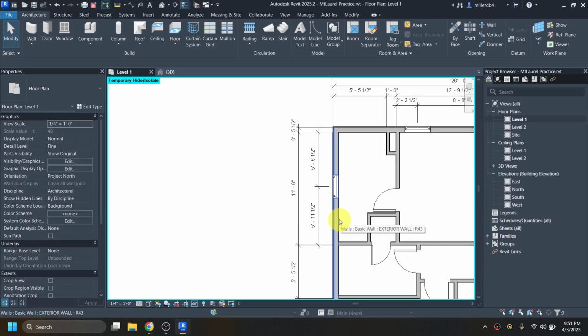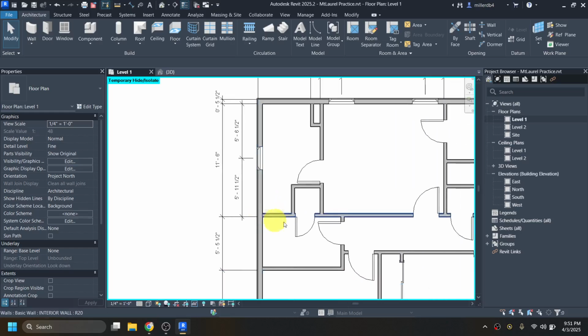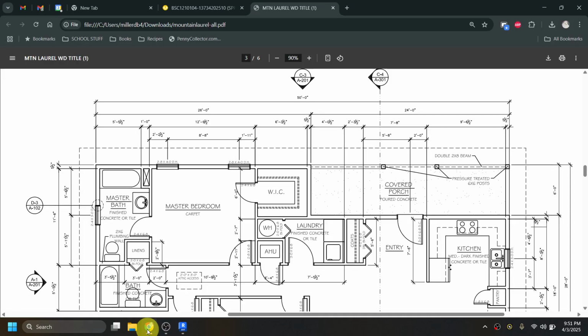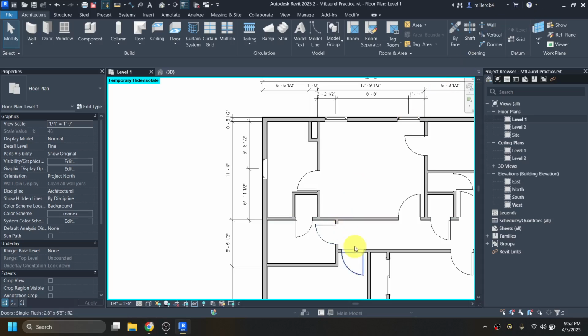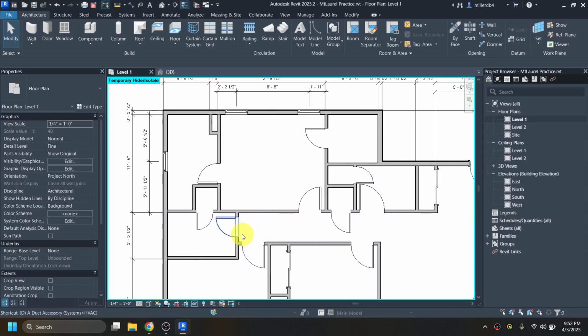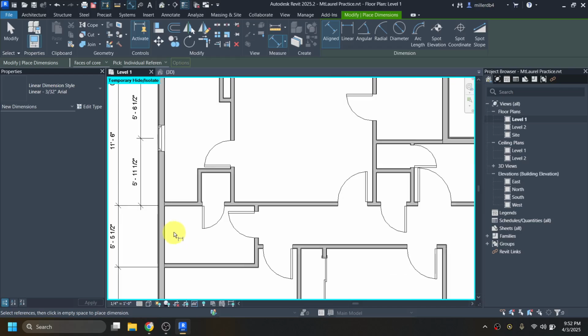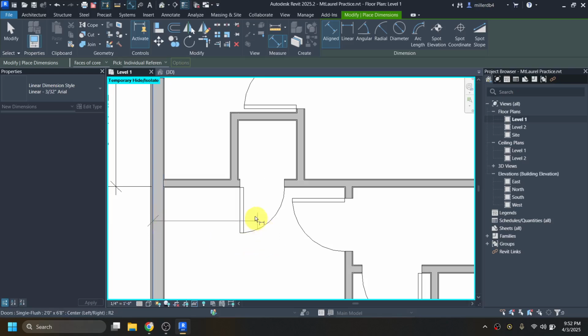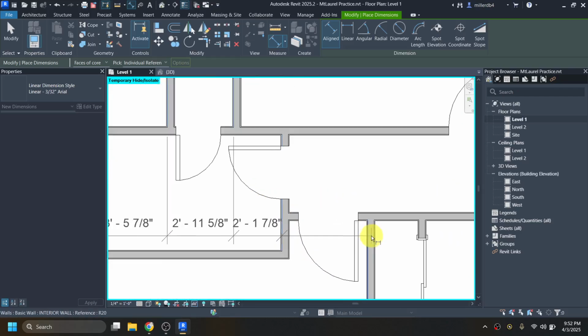Got some interior dimensions to work on as well. Some of them I'll do as lines, some of them I'll do individually. So we've got sitting in the like hallway here, kind of a big string of them. So I'm going to do keyboard shortcut DI from face of stud to this linen closet stud, this other side of the linen closet, the bathroom entry wall.